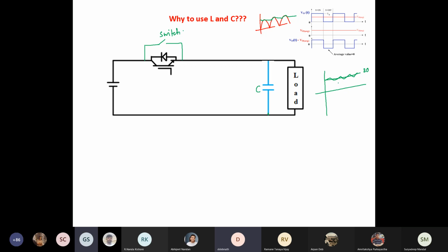Sir, when we are drawing more current through the load, the waveform might collapse again to a square wave. Sir, actually it depends on the capacitor size. The ripple is inversely proportional to the capacitor size. If you put a high capacitor, this actually goes out. Okay. Well, I'll come back to a more serious problem. It's remaining.